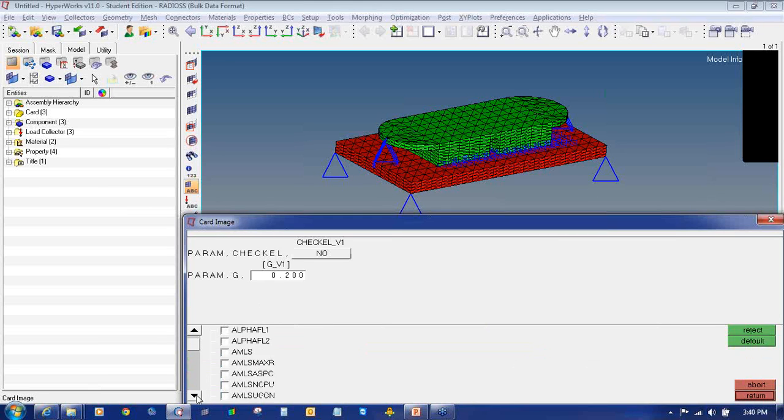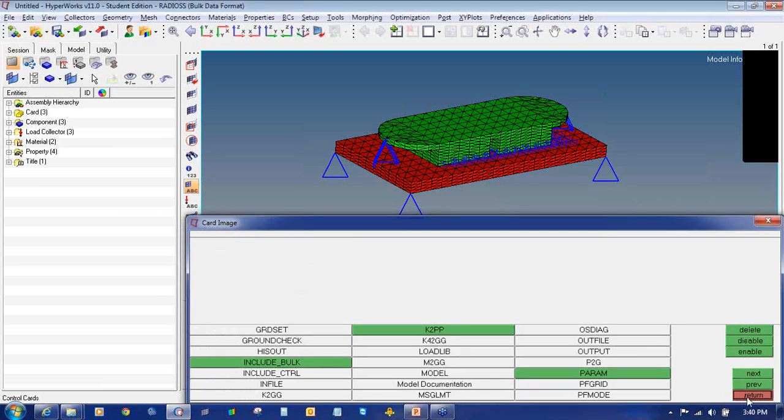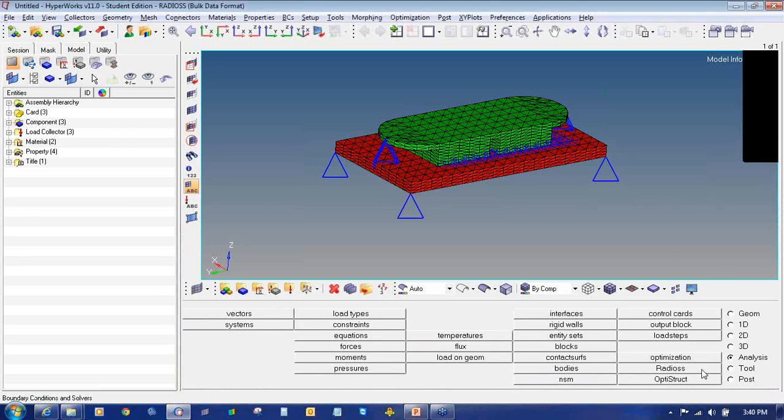Again we will go to param and select FRIC. Here we will input the value as 0.05. Friction factor 0.05 is used to scale the friction coefficient from DMIG data entry. Then we will click on return twice to exit the control cards.